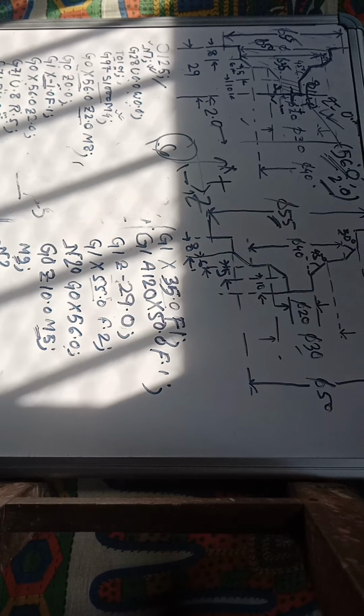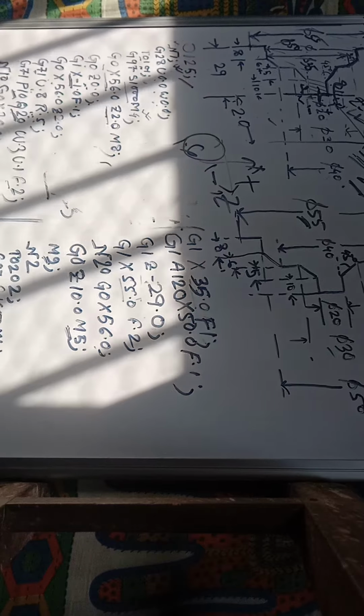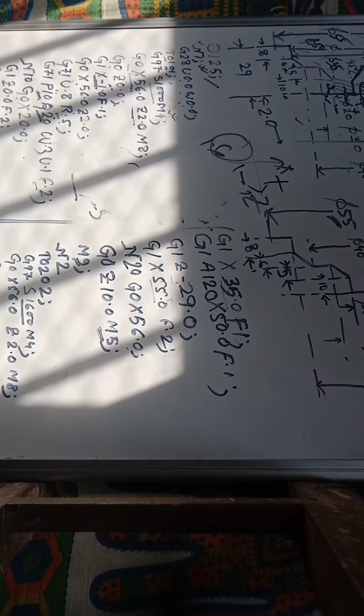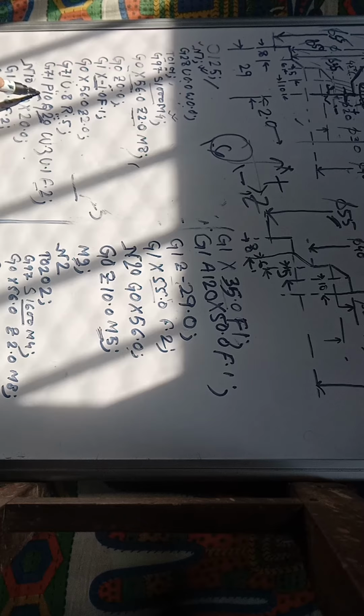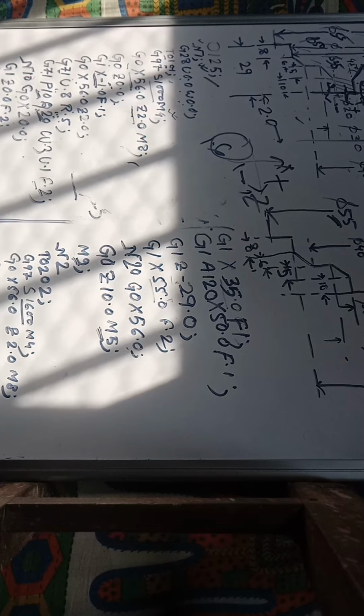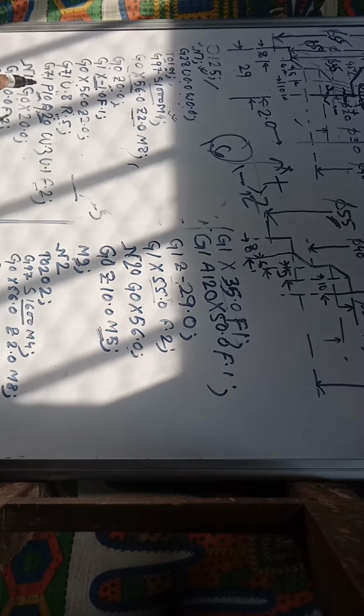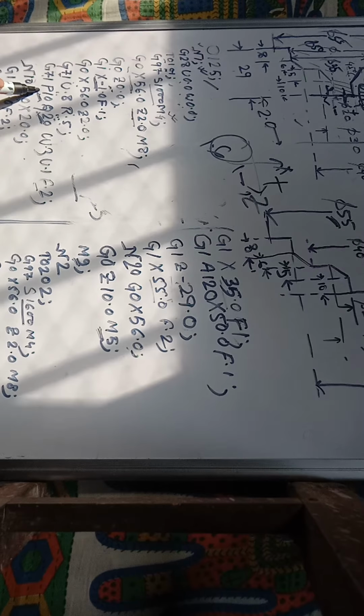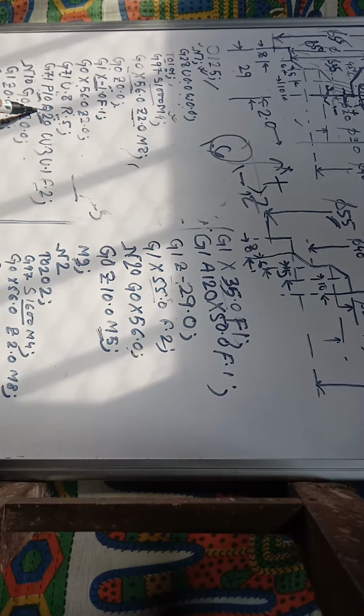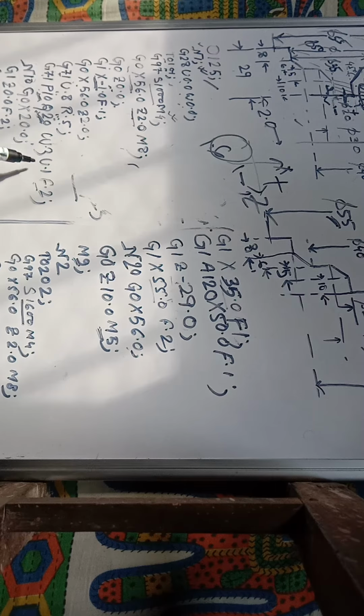After that, we have given G71 P10 Q20. So what will be done here? P10 is the starting of the sequence and Q20 is the end of the sequence. W, U, feed, F represents the feed.